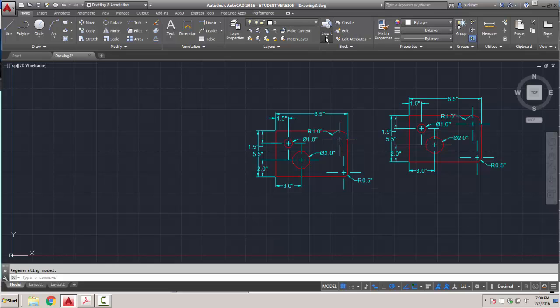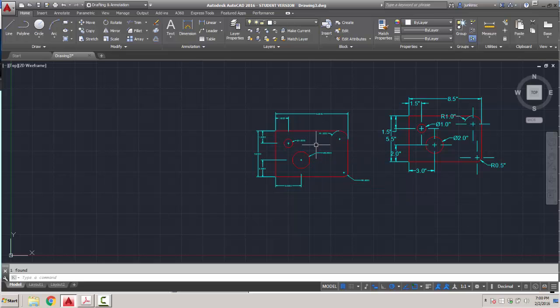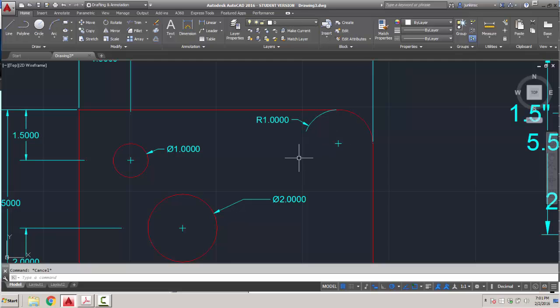So anyway, with a little bit of difficulty, we are able to get those in. So any DWG file, anything can be a block, and you'll notice when I bring these in and select them, everything selects. So again, what happens if I want to manipulate this now and take it apart? All I do is type in explode, and now everything is back to individual pieces.